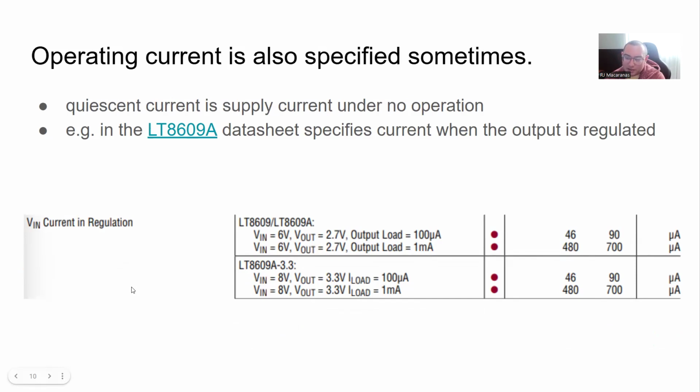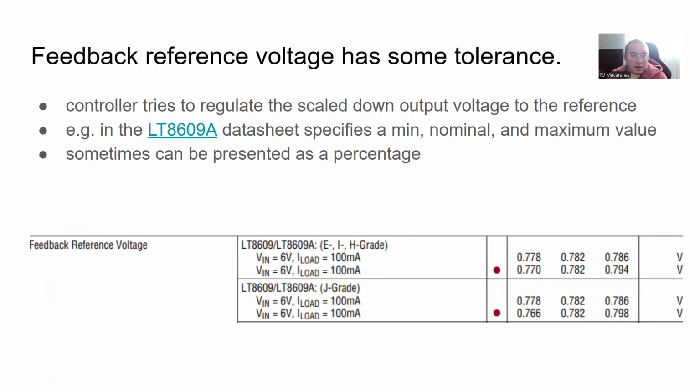So it's just something to keep in mind, right? This might be negligible depending on your input voltage source. Maybe it can handle on the order of microamps more current, but maybe it can't, right? It's just something to keep in mind. You need to know what this input voltage source is capable of before you start using all of these ICs. All right.